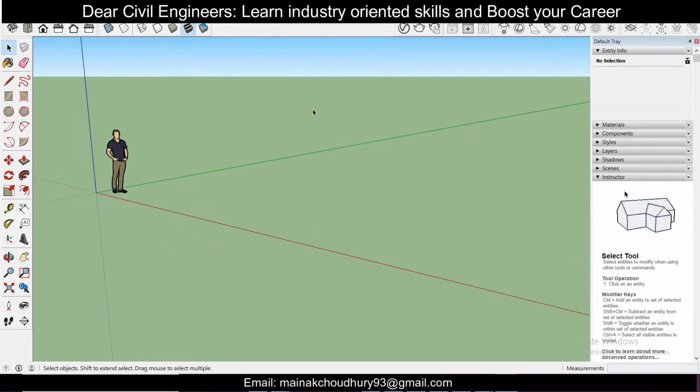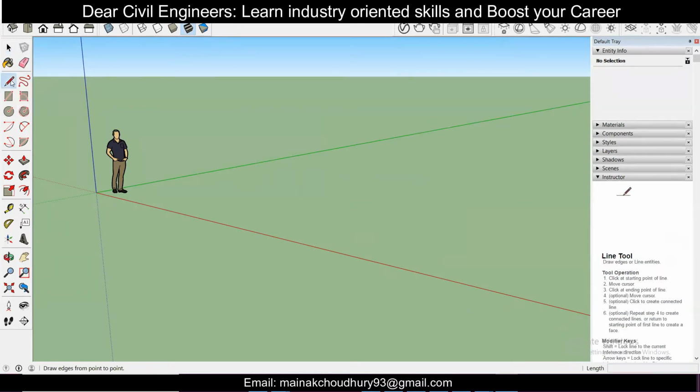So like this it works. So now we have learned a bit about the user interface, and also we have learned how to set the units, and we have used some portion of the line tool. So let's use the line tool in detail now. I've clicked on this line tool here, and first of all, just click anywhere on the surface.